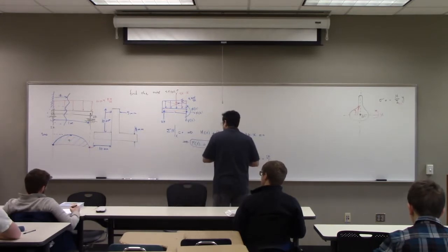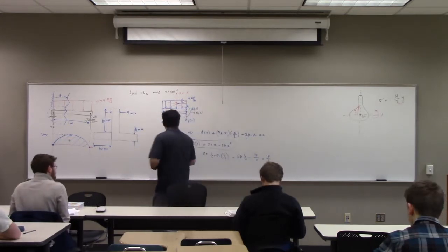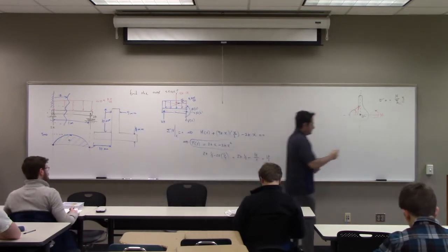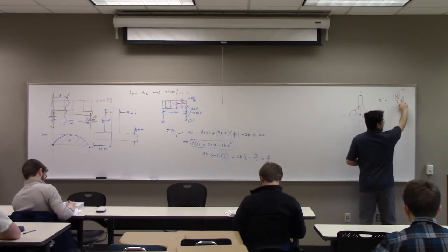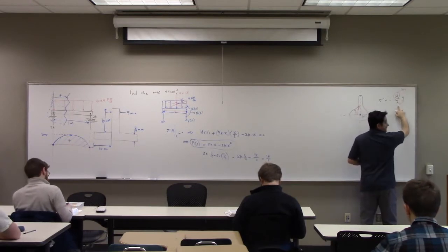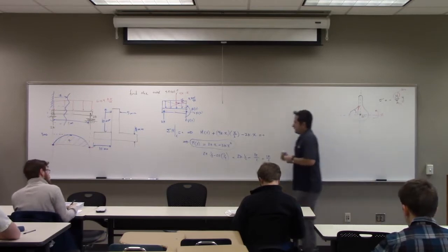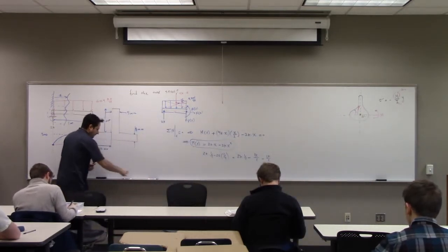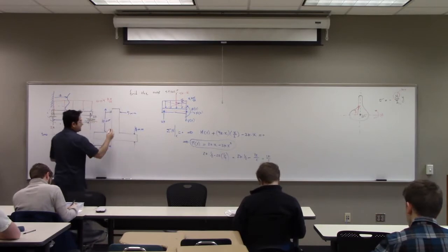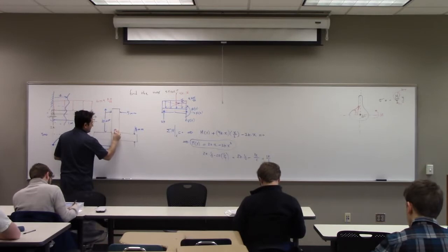So now the next step is I come here and say, I got this 500 at that particular point. And what is y and Ixx? Now let's talk about this. Based on this position, let's say I find my centroid, and the centroid is obviously somewhere here, approximately.